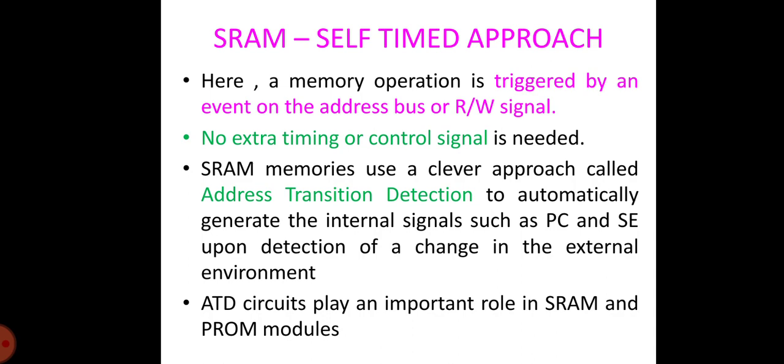Memory reliability depends on the fact that both SRAM and DRAM operate under low signal-to-noise conditions. Maximizing the signals while minimizing the noise contributions is essential to achieve stable memory operation. Another problem in memory design is the low yield due to structural and intermittent defects. A tremendous effort is being made to produce memory cells that generate as large a signal as possible per unit area. Notwithstanding this effort, the produced signal quality decreases gradually with increase in density.